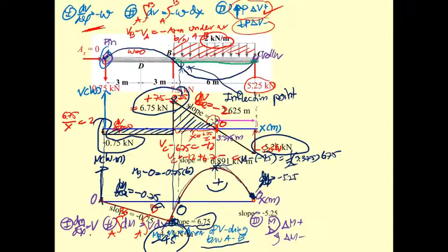And this one goes a little bit beyond the inflection point, making the development length enough for the steel and the concrete. Okay, that is the elastic curve and the reinforcement pattern.